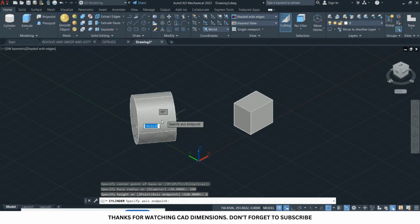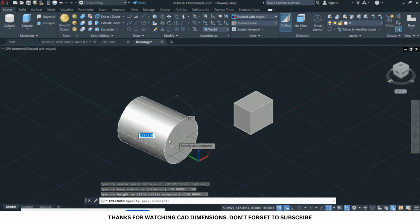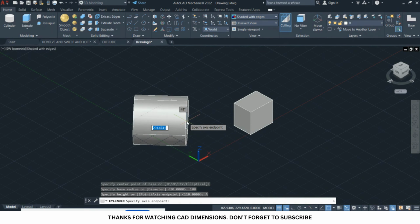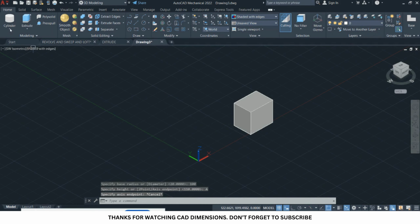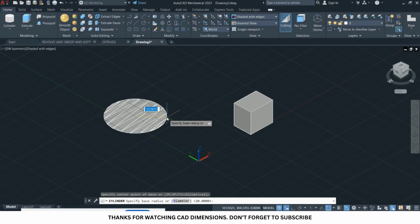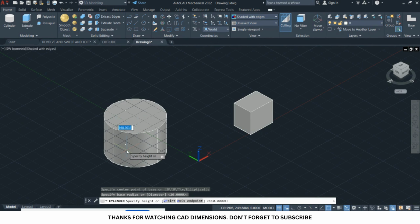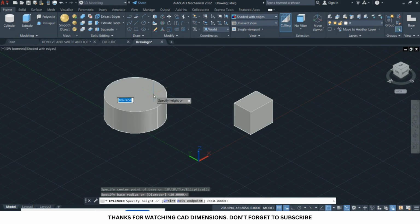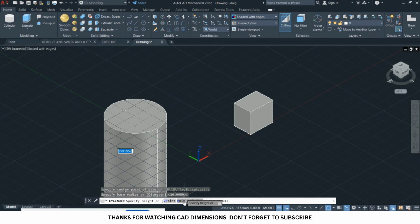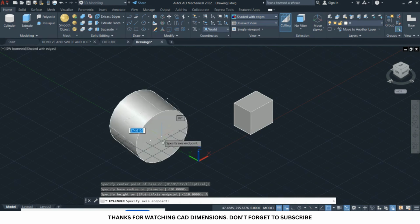If I click on that, I'll be able to change the orientation of the axis, that is the axis endpoint. All right, press escape. I want to show you again. So click on cylinder, specify your point. All right, and you can change the axis. Currently the direction of the cylinder is pointing upwards. If I come down, it means I'm going the negative direction. Likewise, like I said, if you come to the axis endpoint, you can actually change the direction of your cylinder.